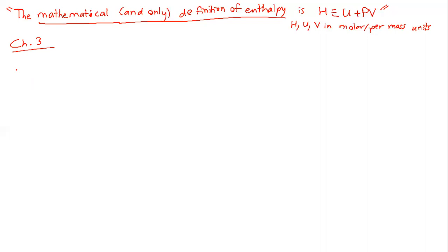Where Aspen Plus is calculating your heat transfer and the work you have to do, those come from internal energy and enthalpy, and those are being calculated based on the property methods you choose. So if you choose the wrong property methods, really your whole process is messed up. It is very important that you choose the right things, because Aspen Plus isn't going to tell you, oh, you chose the wrong property method, this doesn't match thermodynamic data. It doesn't know that. It's relying on you to tell it that.